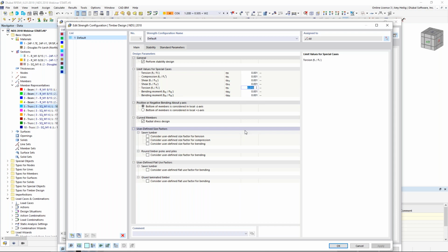And I really just want to skip this. Well, what I can do is to set a higher ratio here, such as 0.3. So as long as my stresses for torsion are below a 0.3 ratio of the limiting torsion capacity, then we'll completely skip this check.